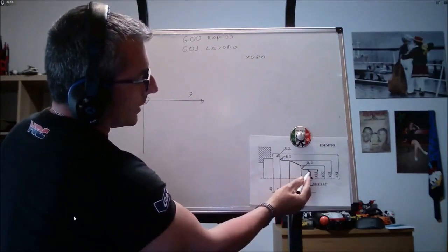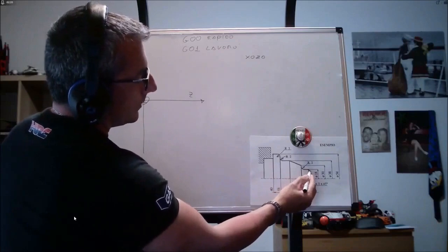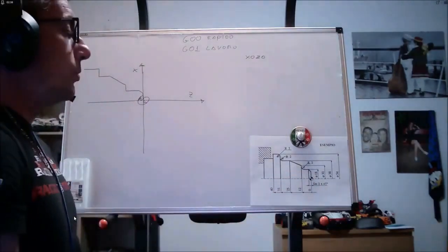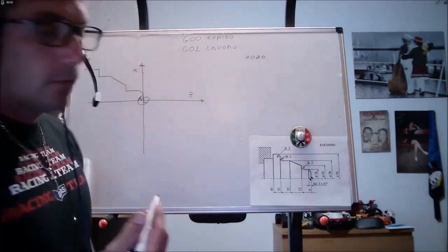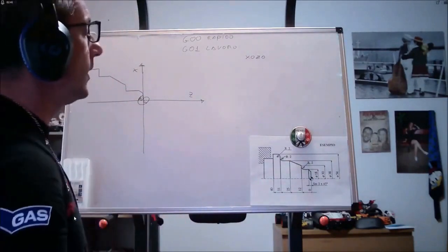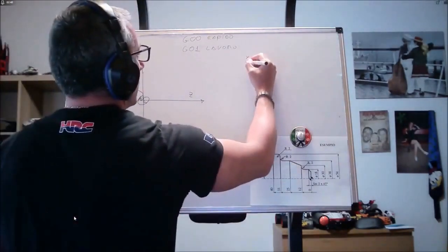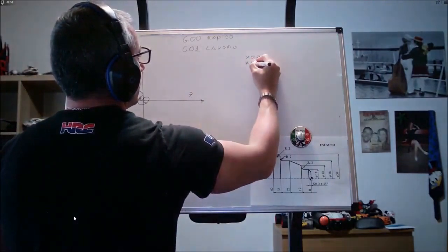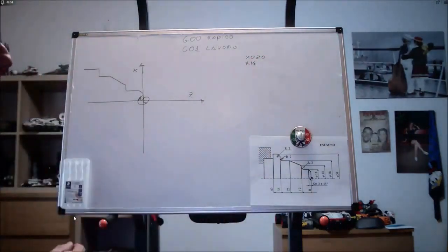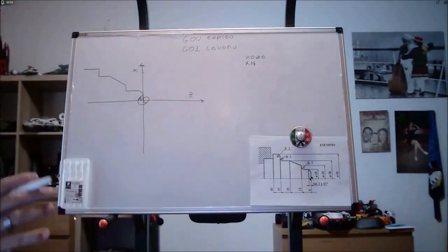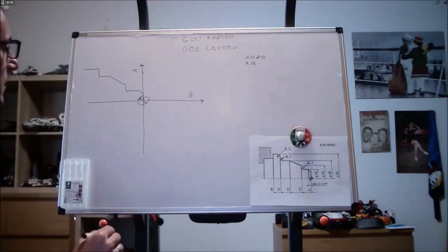So this is a triangle formed by two sides of 2 mm, so it would be natural to say, well, I now go up to X16, 18 minus 2. On a lathe, I go up to X14. This is because, as I explained, the movements in X are diametrical.